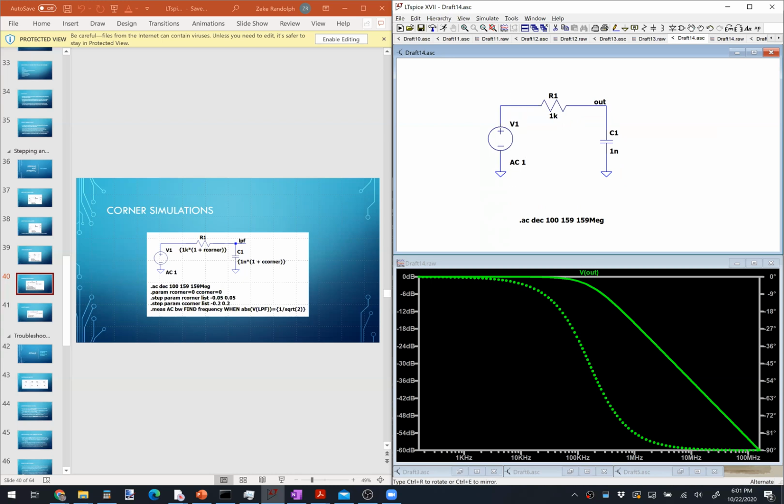Well, one thing that you could do would be to do some hand math, to do some hand calculations. But for a sufficiently sophisticated circuit, it becomes pretty cumbersome to do that. Especially, I mean, for a single pole low pass filter, it's not too bad. But if you had, say, a 4-pole or a 6-pole filter, it can get pretty tedious. So we can kind of shortcut that a bit by just using the simulator.